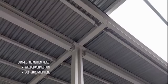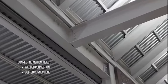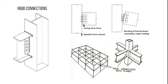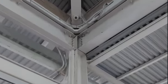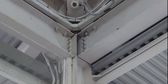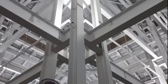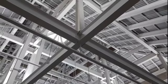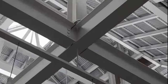The connecting mediums used to connect all the structure are welded connections and bolted connections. These connections are also known as rigid connections. Rigid connections are essential for resisting lateral and rotational forces, providing stability to a structure, and facilitating the transfer of loads. A steel plate is welded to the end of the beam, and it is then bolted to the supporting column. This configuration provides a rigid connection and allows for the transfer of bending moment between the beam and the column.